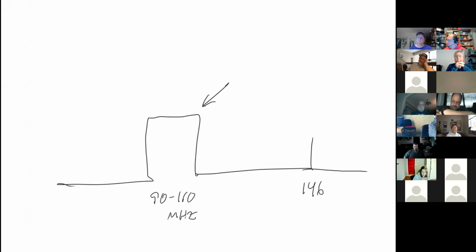So one thing you can do is put a bandpass filter on that radio if you really want it. Basically it's unable to reject the strong signals outside of the band. One thing to do, again, you can put a filter on the outside of it. If it actually has an external antenna, you can install a filter on the radio, linking through to that radio, and that's the radio that needs the filter.